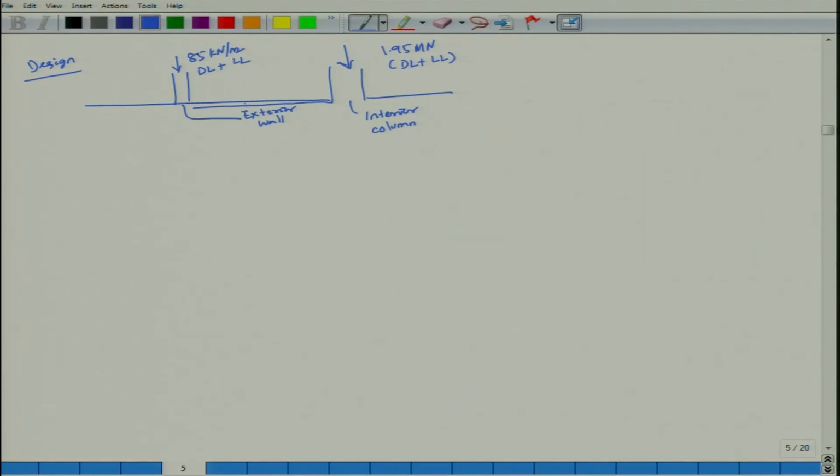There is a gap, generally 0.15 meter of floor slab. This is a sandy soil, sand, gamma is given 17.5 kilonewton per meter cube, and below 2 meter there is a water table.